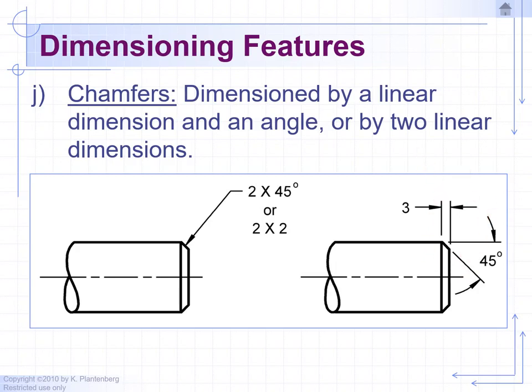Next, once again, note that there is a space between the 2 and the x, which signifies "by", so 2 by 2. If there was no space between the 2 and the x, that would indicate 2 places, or 2x, when you're talking about quantities. To avoid assuming that it's 2 places, we put a space on each side, so we know it's 2 by 2.